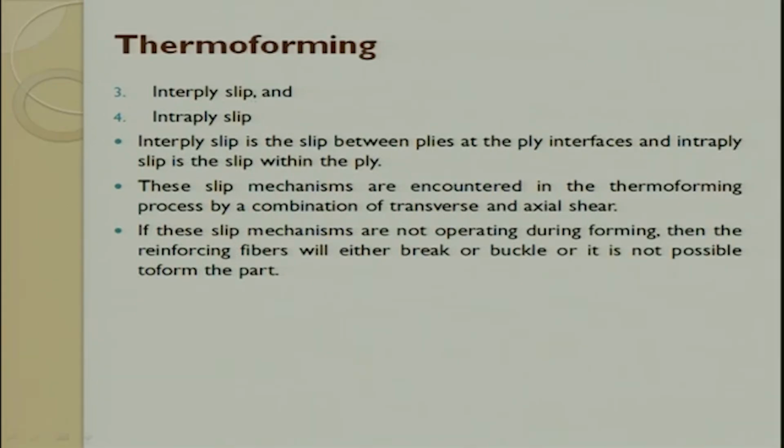Next, interply and intraply slip. Interply slip is a slip between the plies, and intraply is within a ply. So, these two are the other mechanisms which are very, very important. The slip mechanism encountered in the thermoforming process is a combination of transverse as well as axial shear.